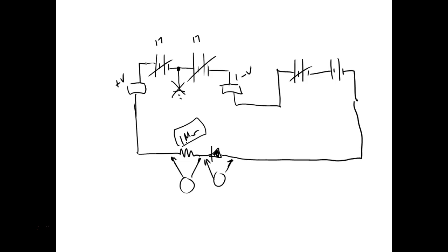So that means if we take one of these diodes in a power supply and we don't have enough PIV rating, as soon as we turn it on the first time, it's going to pop all of them, right? And that's a peak inverse voltage rating. So it has nothing to do with RMS. So you've got to know that peak voltage that it breaks over at, right? We're not dealing with RMS or average or anything like that. Normally we try to double that, just to be on the safe side, also to help if there are any surges, which are hard to get through.